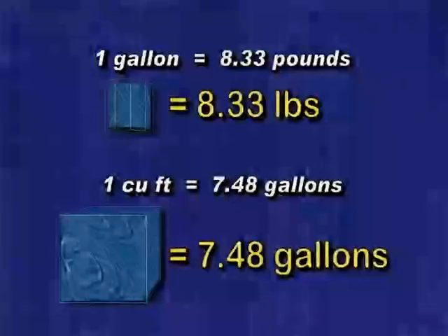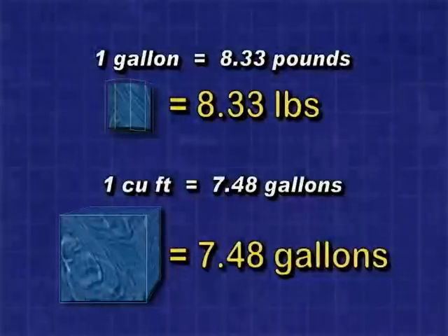And, of course, you know that the boiling temperature of water is 212 and the freezing temperature is 32 degrees. And again, of course, that's in the Fahrenheit scale. And another item you should notice, the volume of 1 cubic foot of water is about 7.5 gallons. Now, when we look at vents and traps, and I want you to read through that and understand what they're talking about, the main thing that vents and traps are used for is to trap sewer gas. If you've ever done a little bit of plumbing on an older house and you've undone the plumbing system, pretty soon you'll notice that the sewer gas comes up and it's pretty stinky.